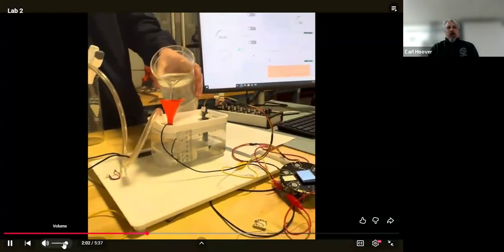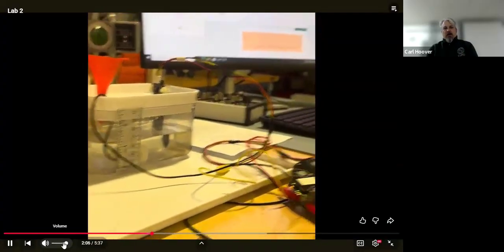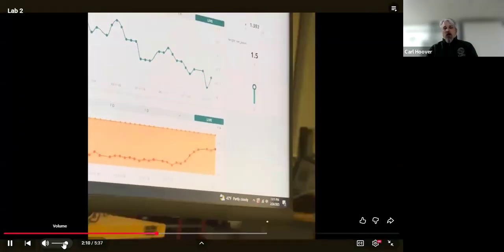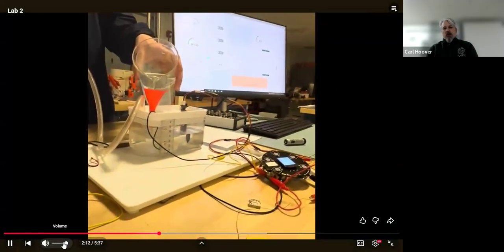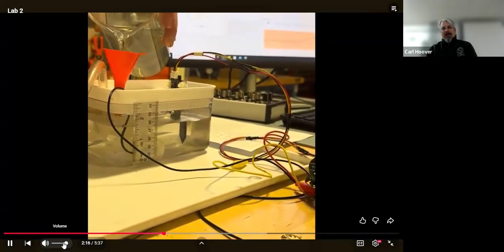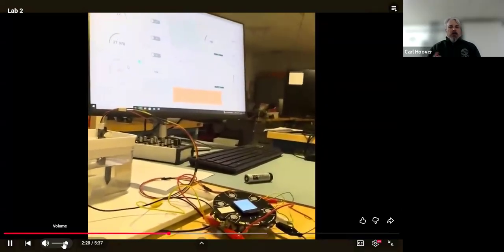We see a tank that has water in it. We can add some water. Water goes up, and ultimately, we want to be able to control a pump set at 1.5 inches plus or minus a quarter inch. We want to be able to turn on a pump to pump excess water out when the water gets too high, using that Arduino, using a dashboard and a feedback loop.